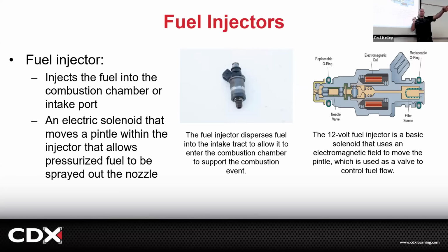I heard it tick, but I didn't see the fuel pressure drop. The fuel didn't flow through the injector. Now, what's the fix? Maybe replace the injector if you wanted, like when we were broke kids and we'd be like, oh, we'll work on the Neon today, and we'll take it out and try to tap the rust out of it and get some brake clean and carb clean it up. And you could try to bring it back maybe, but maybe not.